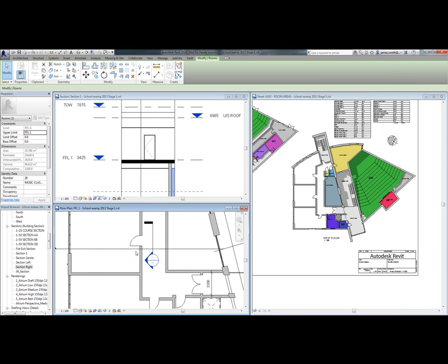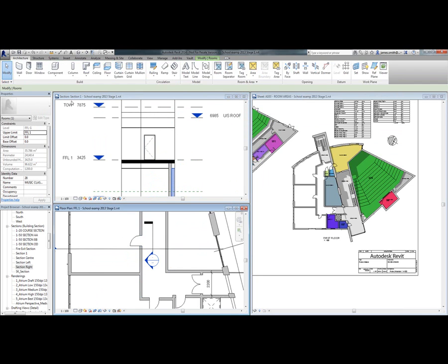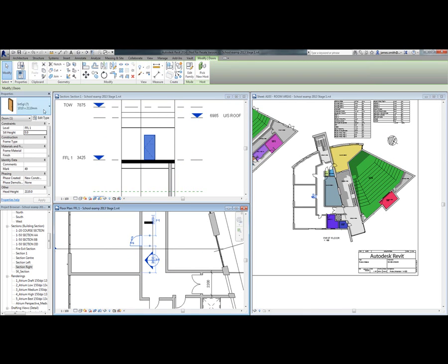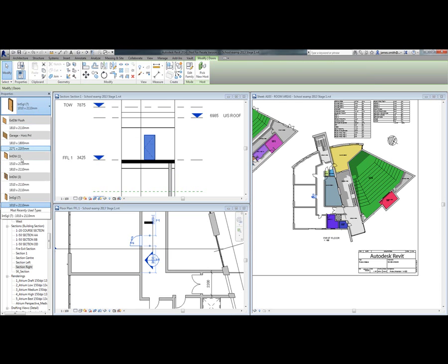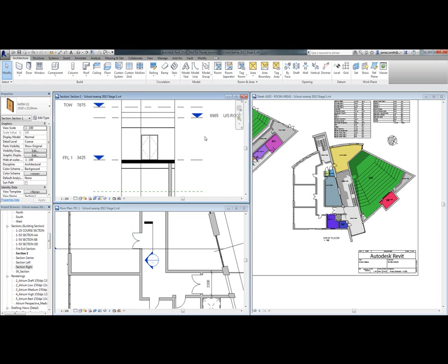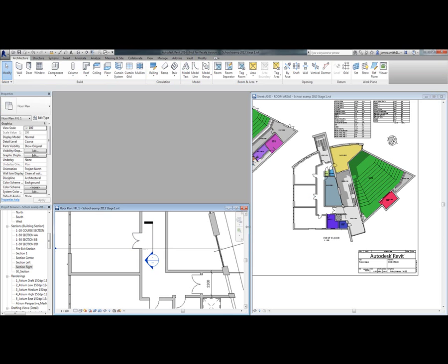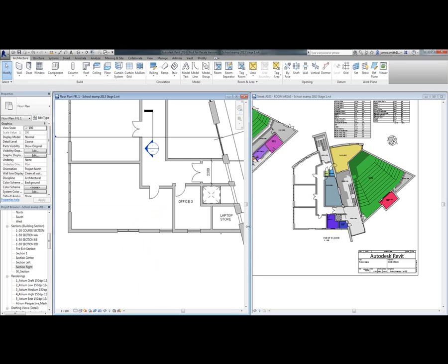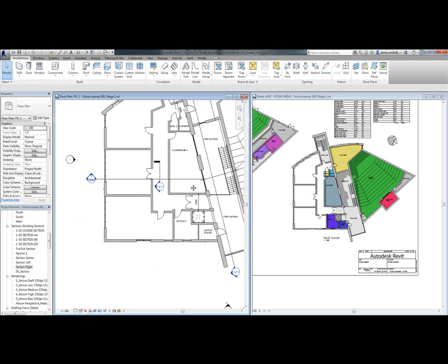So I might want to put this on the drawing later on just to demonstrate perhaps there's a particular door or a particular unit. I can now go back to my architecture tab, and if I select this door, it brings up the properties. I can then go down and say I wanted a double door for this particular one, and you'll see it's automatically updated. This just shows the ease of function and how it's all relative throughout the project. Once we've done that, we're ready to look at the project in a bit more detail.